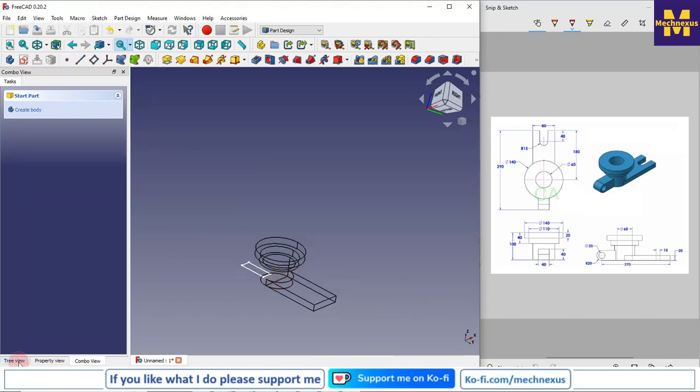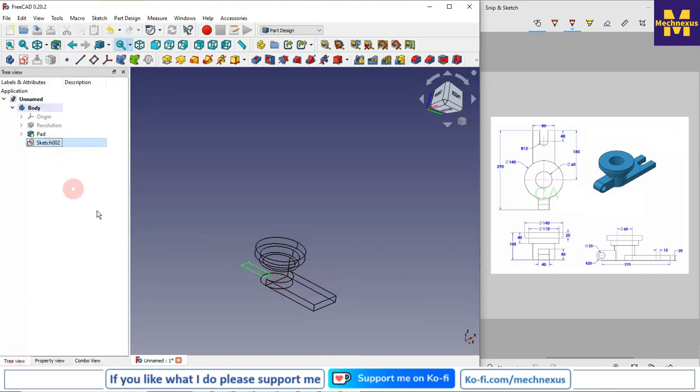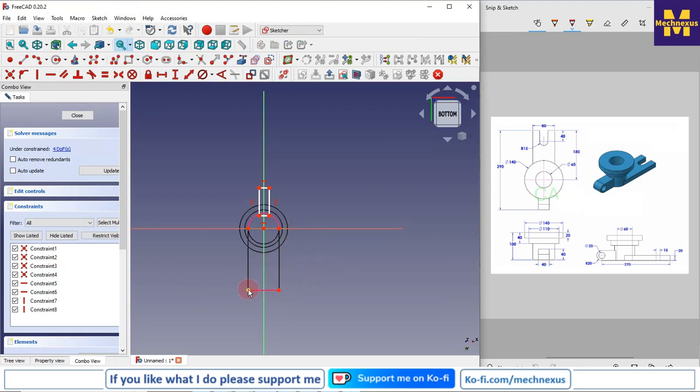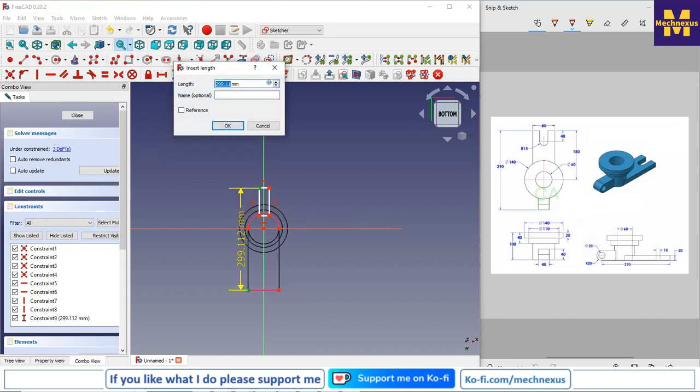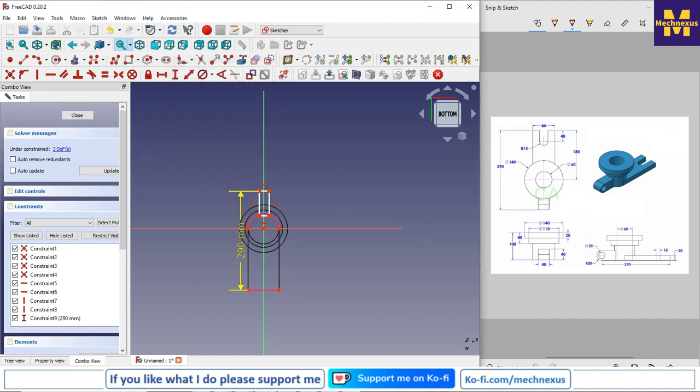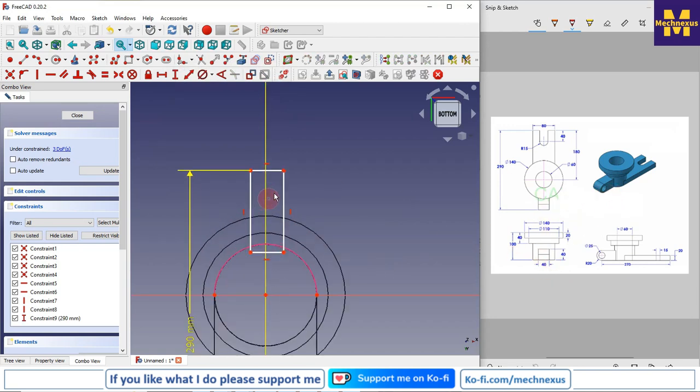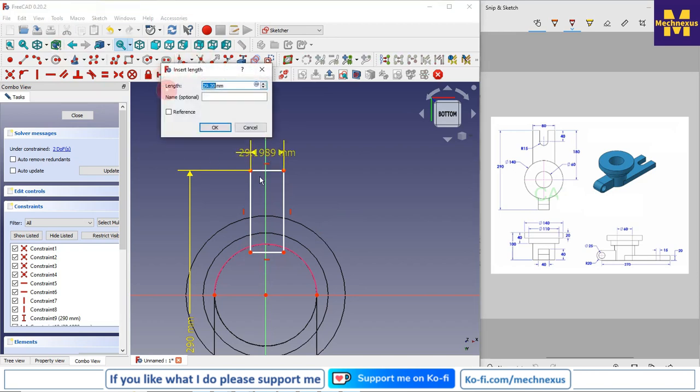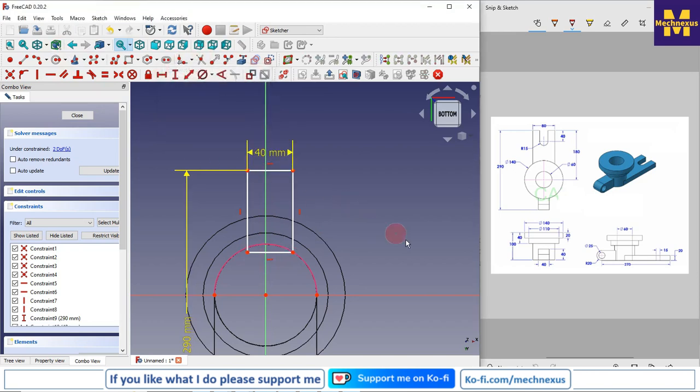I will again edit my sketch. So this is the 290, and this is the 40. So I will select this line and give the dimension 40, and I will make it symmetric.